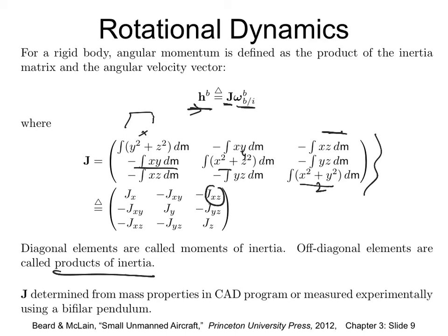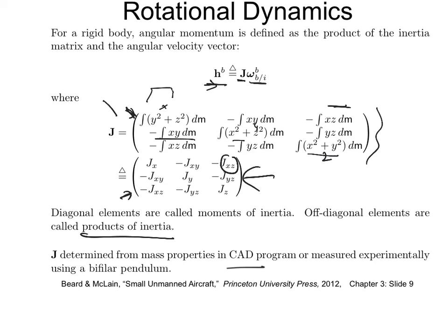So these are J. And don't worry, we'll give you this matrix so you won't have to compute it, because these matrices are computed using wind tunnel tests, or if you exactly know the mass distribution of the vehicle. I'm just providing you the J matrix, as given by the supplier or manufacturer of the aircraft. J is determined using CAD programs or experimentally, and if you are interested, I can put up a paper or a note which computes these. I'm not particularly interested, but if you are mechanical engineering folks, this will be of much interest.